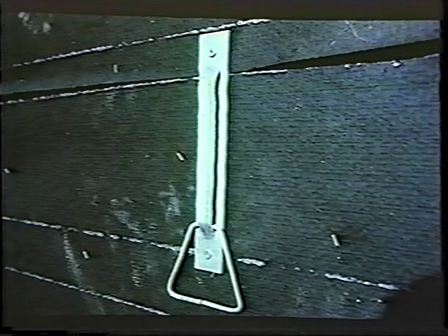It's important to attach the tie to the backing properly. When building with wood studs, nail the tie to the stud. Nails can easily pull out of the sheathing, so they must penetrate the studs. Ties used in concrete masonry backings must be properly embedded in the mortar joints. Wire ties are used with a backing plate. Attach the plate to the stud with 2 nails.